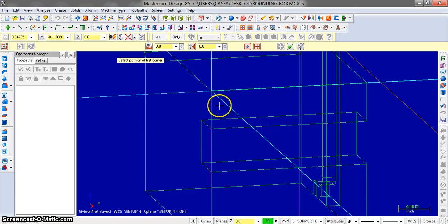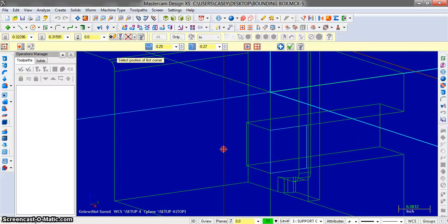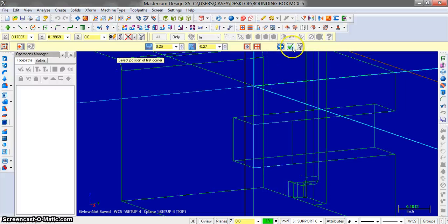Click this point right here, right below your top bottom right. You're going to click right below it, which is this one right here after the cut with the extrusion you made. So click here, and to get the dimensions, it's going to be length is 0.25 and height is negative 0.27. So in short, the same dimensions for this cut. That's fantastic. You're going to click the green check.